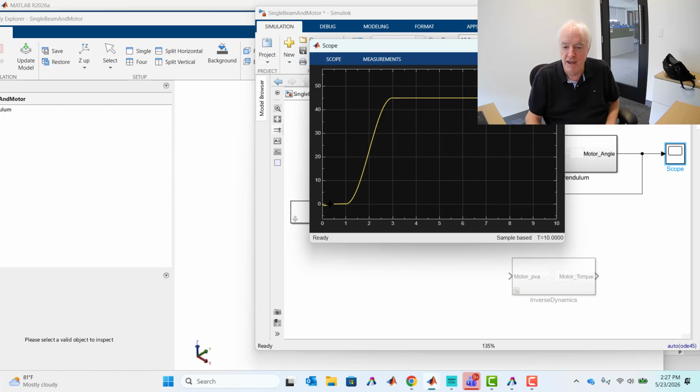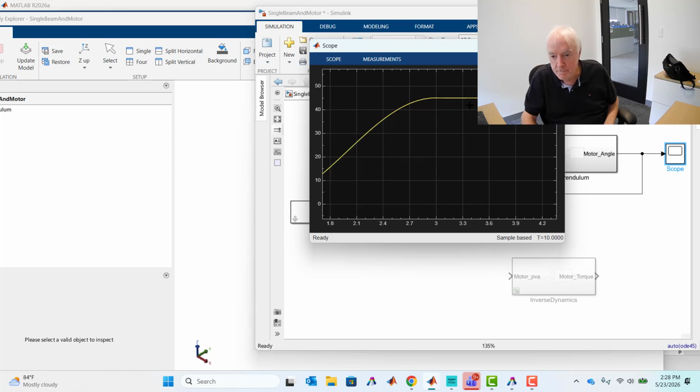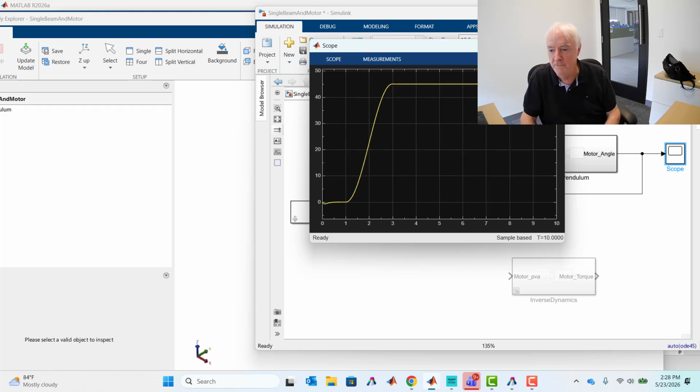Got an interesting little lag right there. And again, I might save this for a video much more dedicated to PID algorithms, but that I is kind of the systematic corrector, and it's really kind of the integration of that error builds up the force, or what's in this example, torque, that would prevent it from ever sagging. Right, so let's not worry about that right now. I'm much more interested in what's happening up here at the top. Right, so that looks pretty good, right on 45.